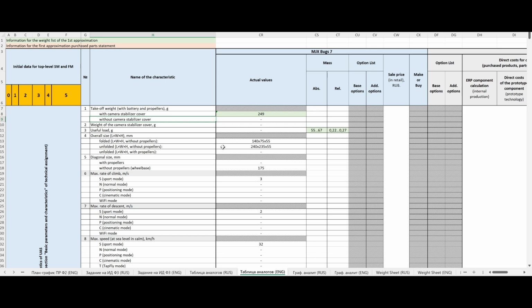Firstly, due to the difference in the payload ratios already mentioned above, which can be several orders of magnitude. Secondly, the formulas for human-controlled devices take into account the life support systems and units and accommodation of the crew and passengers. And thirdly, the strength standards, in particular the reserve coefficients used for manned and unmanned aircraft systems, differ.